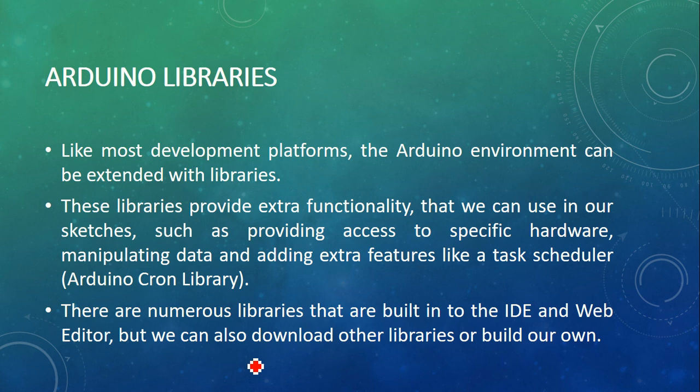For example, I have this experience of using Arduino. I used a special temperature sensor that uses a separate library. If you don't copy or install the library inside the Arduino IDE, the temperature sensor that I used will not be recognized. So the library is very important for the Arduino IDE to recognize this particular sensor or particular output. So that's the importance of providing libraries for your projects.